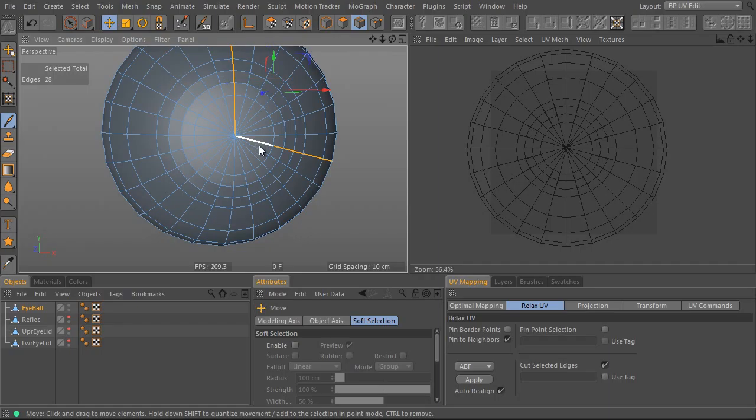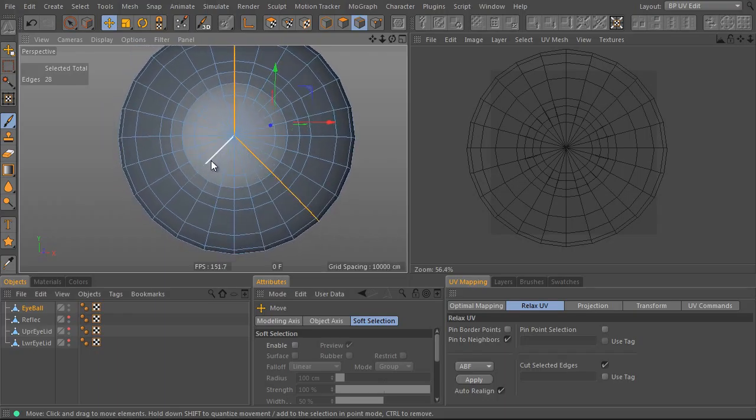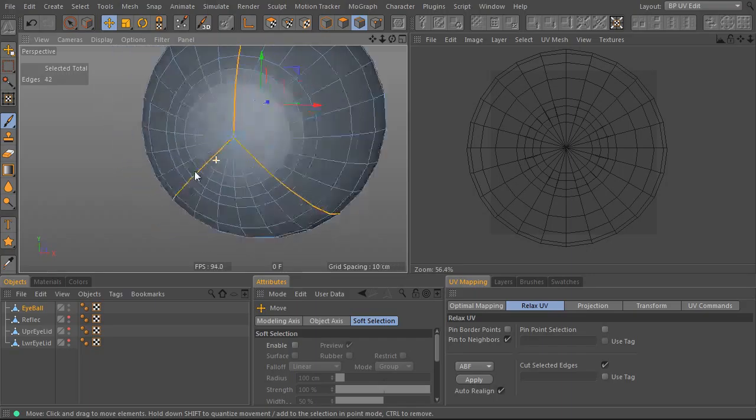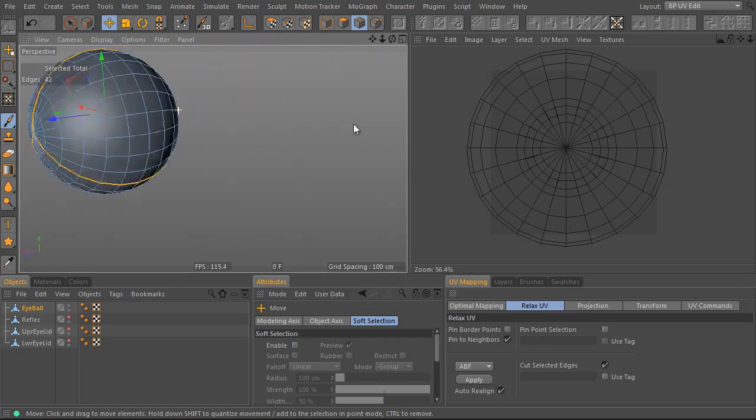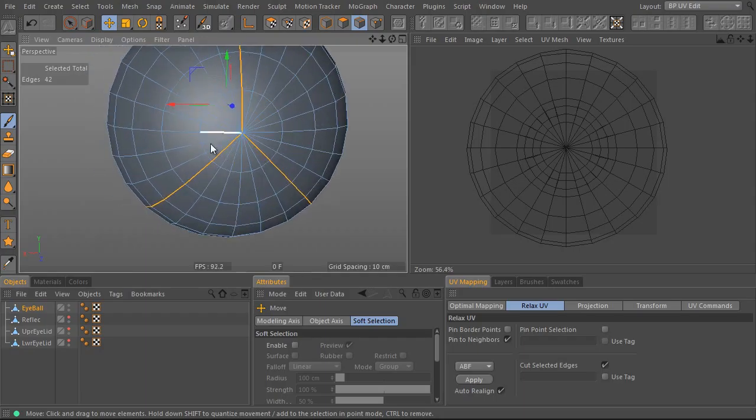For example, I would like to cut here, and 1, 2, 3, 4, 1, 2, 3, 4, and here, double click, so we get a loop. And on the back side, I would like to get rid of the triangles. Those are always messy. Control and right mouse click and move to deselect there.